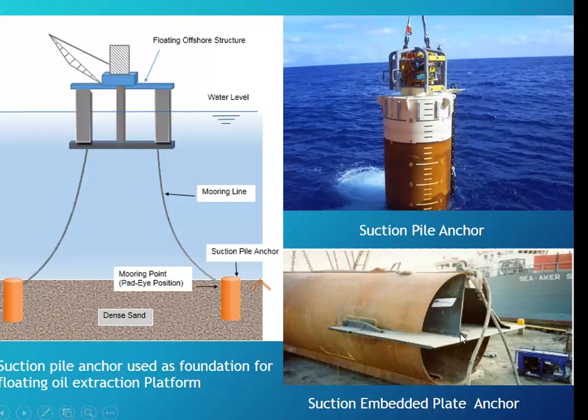Additional under pressure is required to overcome the added soil resistance acting against the plate. After installation to the target penetration depth, the caisson is withdrawn, leaving behind the vertically oriented plate. That plate is again used as the foundation of the floating offshore structure.